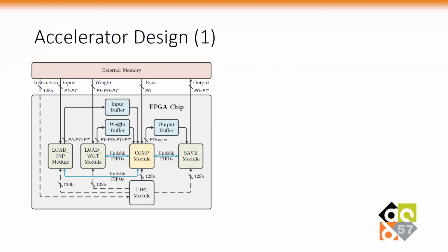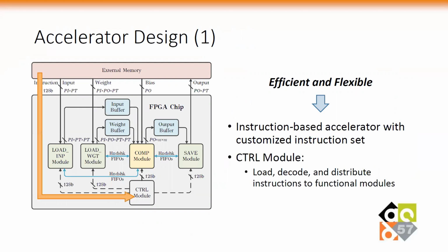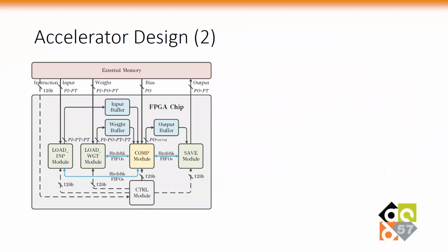Now, let's take a look at the accelerator design. We propose an instruction-based accelerator with a customized instruction set. In the accelerator, a control module will load instructions from external memory and distribute them to different functional modules. There are 4 functional modules in the accelerator.